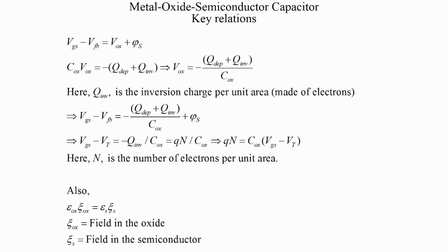So, here are some very important or useful relations. We will summarize all this by these equations here. So, VGS minus VFB. Pardon this usage of S, it is just force of habit. You can say S is the reference potential here. Once we learn MOSFETs, you will understand what VGS is, but just replace all S with just VG. So, you have VG minus VFB, which is the driving force.